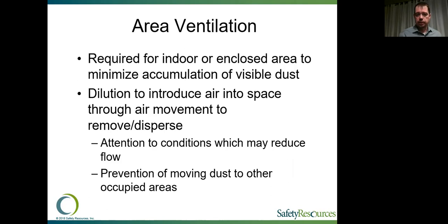Keep in mind that we can't just start blowing this dust all over the place. So again, the dust itself that's generated at the point of impact does need to be minimized as much as possible. And the ventilation is basically just allowing that air to move more efficiently through that space, which would then reduce what their overall exposure is going to be. But keep in mind, there could be certain conditions within that space that may also reduce the flow of air. If I am providing ventilation in a space and it's necessary that I have doors or windows open that allow that air to freely move, that's part of my review of the workspace.